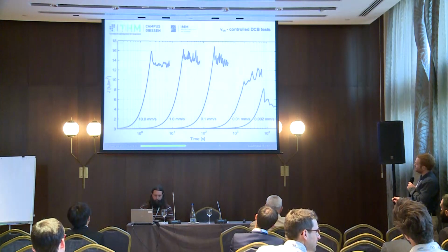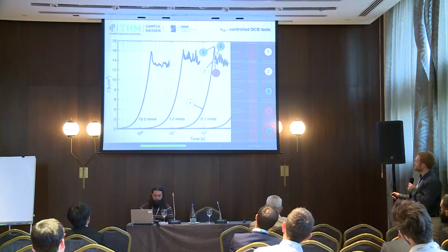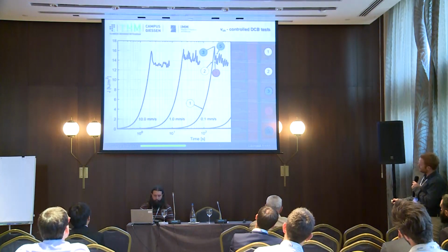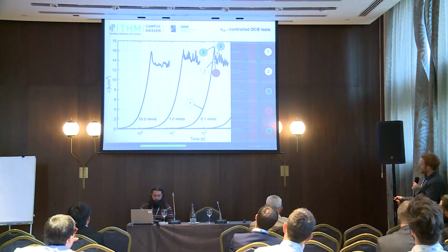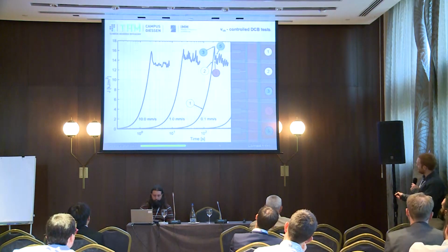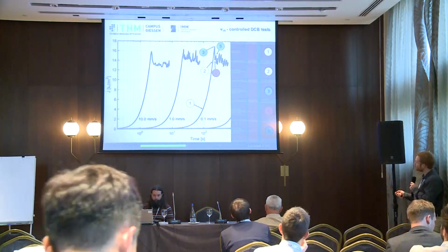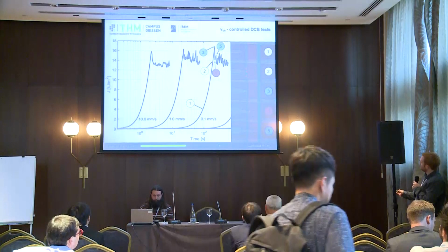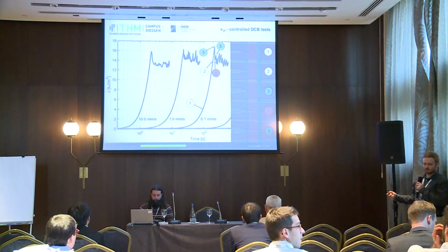So we now take out this curve here to look at the pictures made from the side to see what's happening. Picture 1, you see the pre-crack gets visible, and at picture 2, distinctive necking and blunting of the crack tip appears. We have a hyperelastic material, and from picture 2 to picture 3, crack propagation starts.